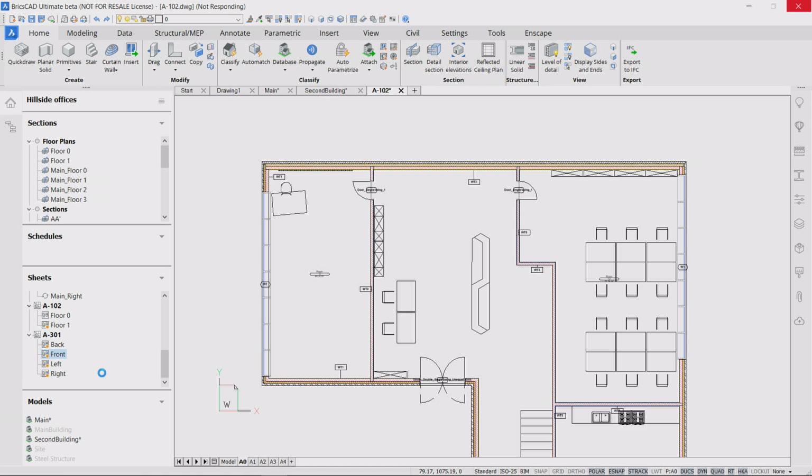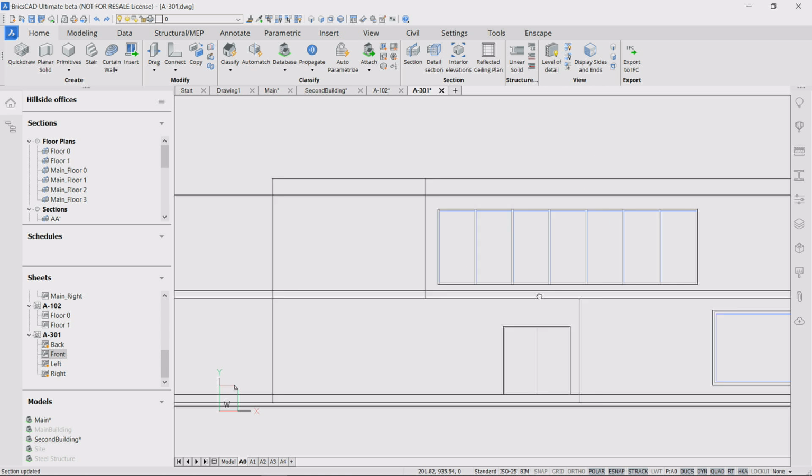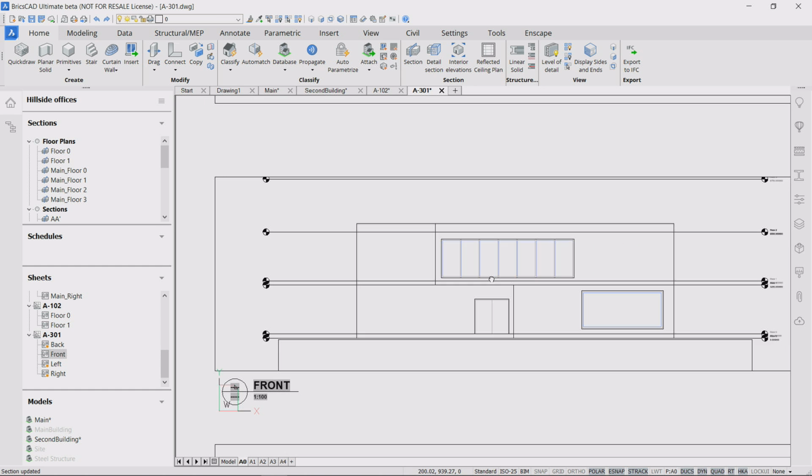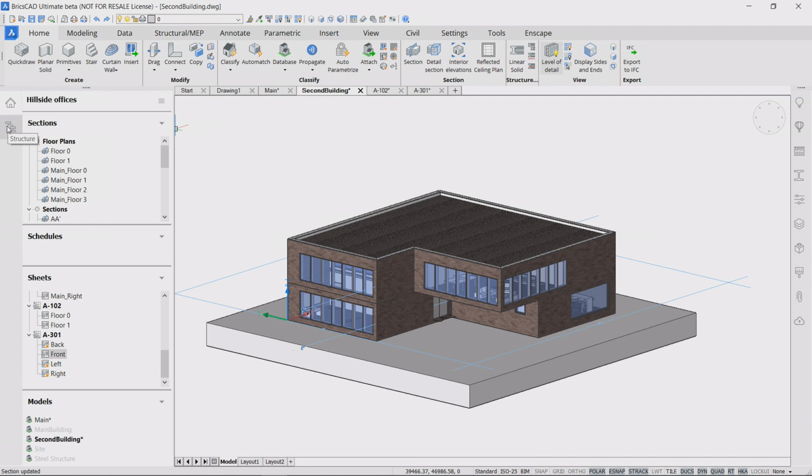This we will show on an elevation. If we go to an elevation, then you see that if we wait a bit and update it first, I guess, then we see that it is still empty now. But in V20, we have a setting called Generate Elevation Fill.